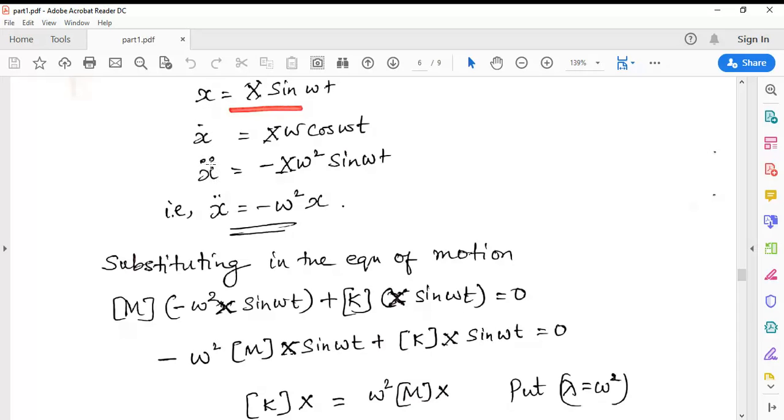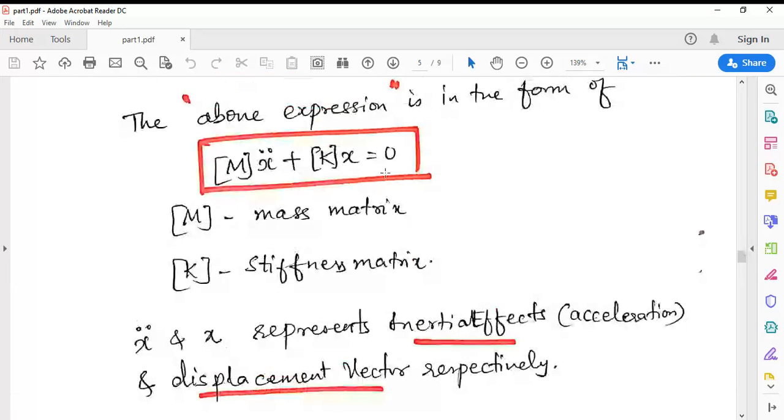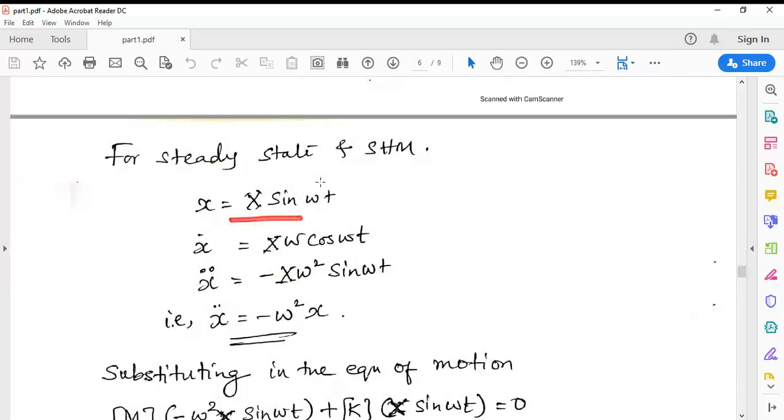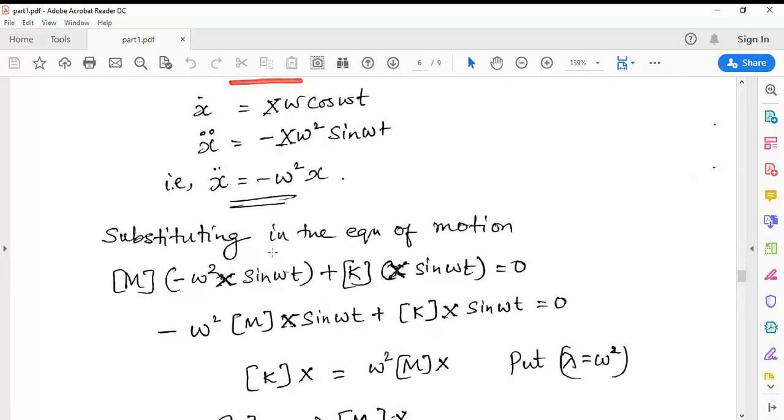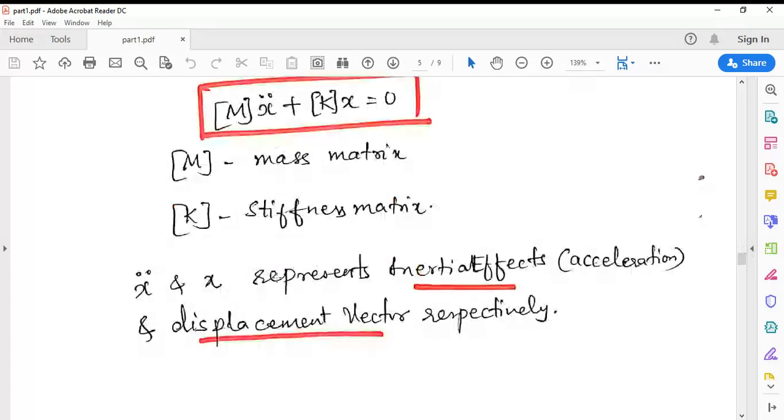Okay, this with spring you call as restoring force. So once you simplify it, it is almost coming back to the same expression. The acceleration component is minus omega square times the displacement. Now coming back to the typical equation of motion in mass and stiffness form, you resubstitute this equation for x double dot in the term m x double dot.